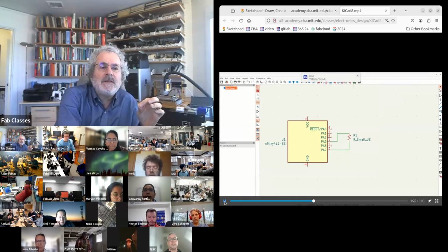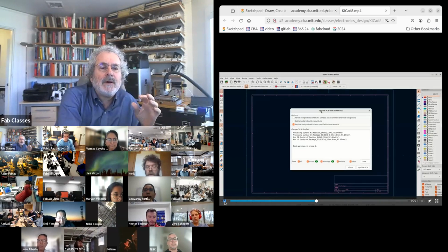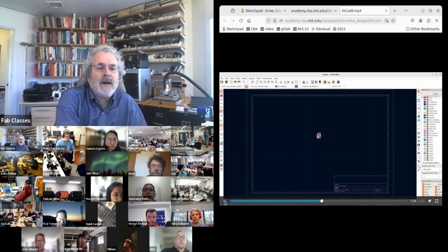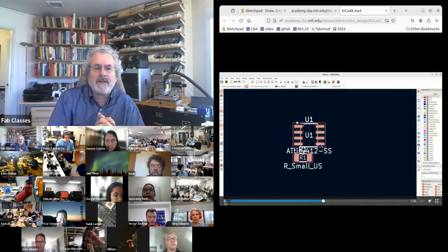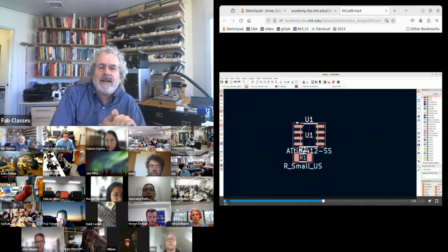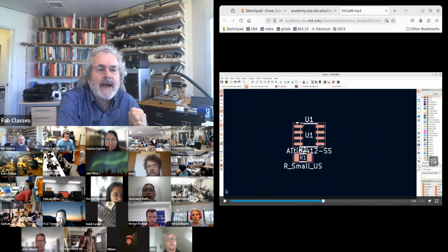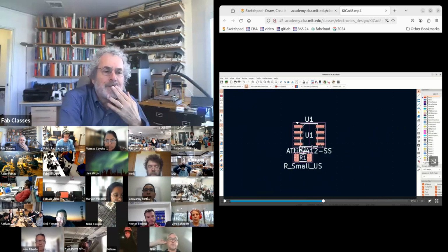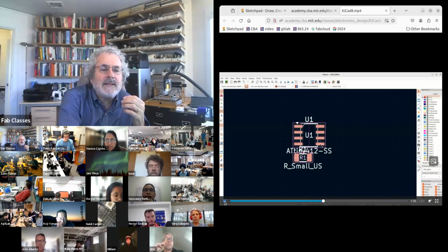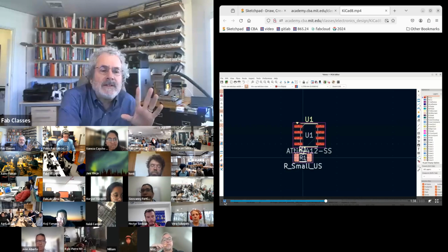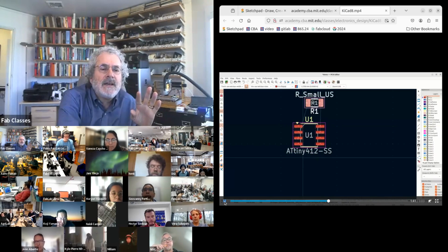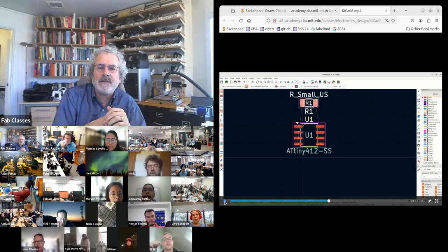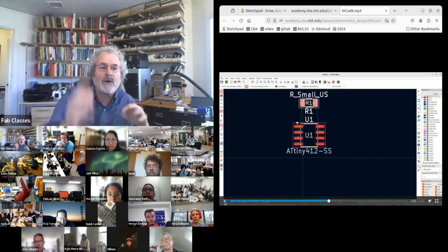Now I'm going to go to the PCB tool. So I just asked to import from the schematic. So now what it's showing me is there are my footprints, the parts I'm placing, and they're connected by what's called a rat's nest, which is all of the wires going between them. And so initially, you can barely see them. It's clearer when you're doing it. You see those lines. Now what I'm doing is I'm rotating the component. I'm placing the component at a convenient location, and then I'm rotating it to a good orientation for where I want to connect it.